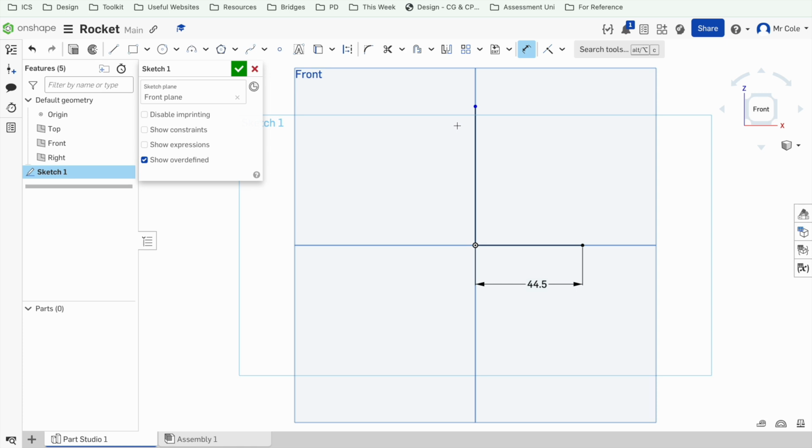So, if my nose cone is 84 millimeters in diameter, I have that extra 5 millimeters on the end for the gap in the wall that I'm potentially going to 3D print. I'm just going to go with the 84 instead, not the 89, which gives me roughly 126 millimeters. Now yours might be different because your diameter might be different. Just calculate it by going 1.5 times your diameter. I'm going to do 126, and there we go.